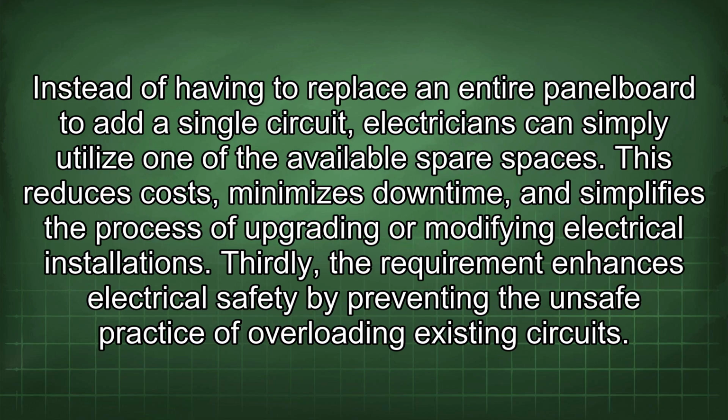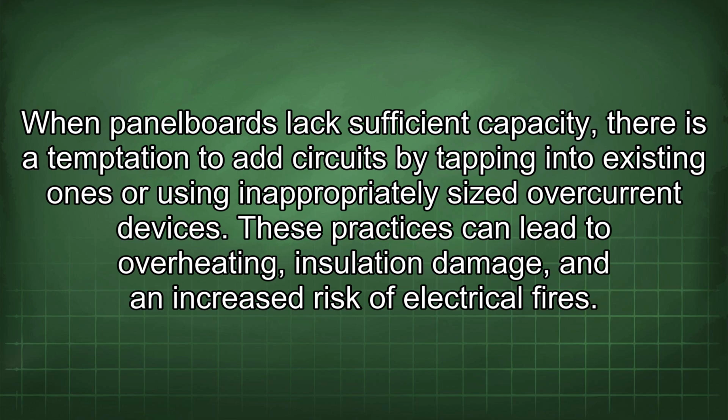Instead of having to replace an entire panel board to add a single circuit, electricians can simply utilize one of the available spare spaces. This reduces costs, minimizes downtime, and simplifies the process of upgrading or modifying electrical installations. Thirdly, the requirement enhances electrical safety by preventing the unsafe practice of overloading existing circuits. When panel boards lack sufficient capacity, there is a temptation to add circuits by tapping into existing ones or using inappropriately sized overcurrent devices. These practices can lead to overheating, insulation damage, and an increased risk of electrical fires.